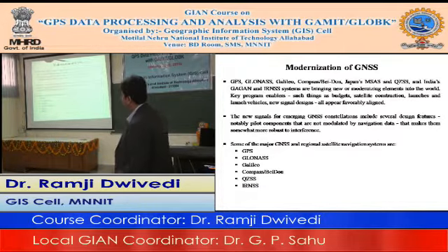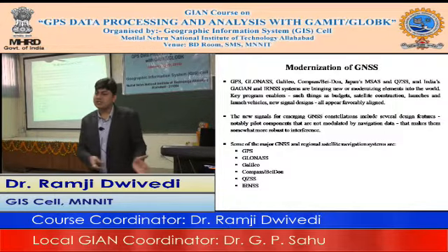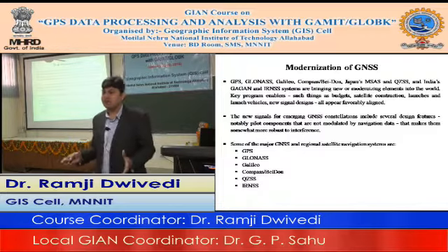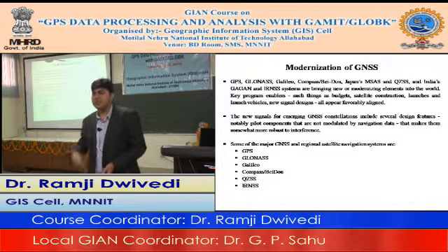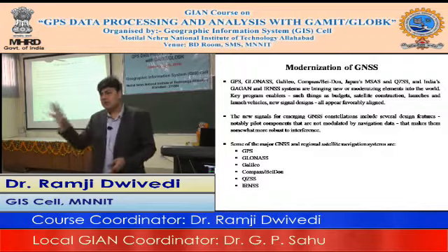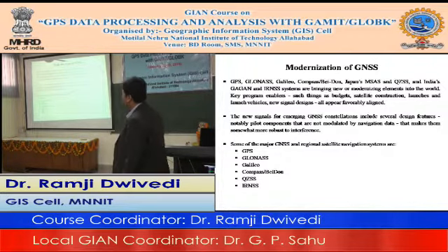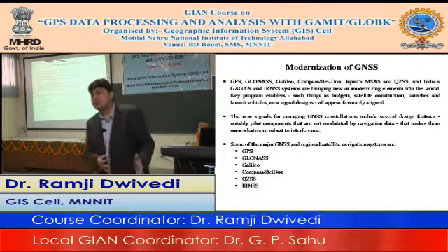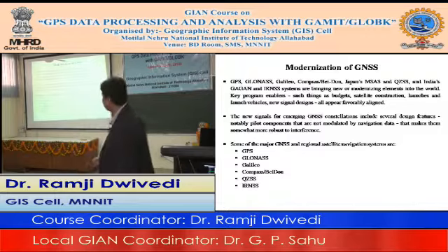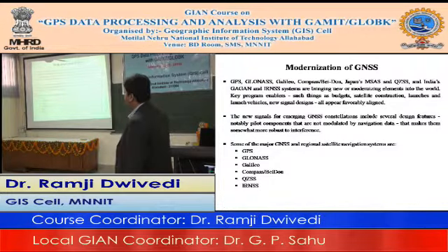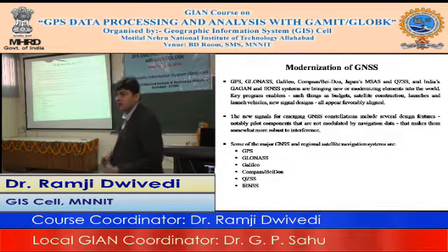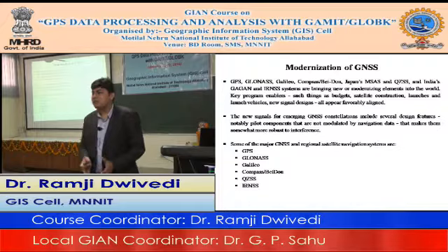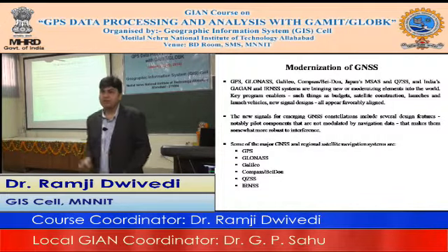Okay, so another section which we are discussing is the modernization of GNSS. Nowadays, if you purchase, let's say we have purchased a base station called NetR9, which has the capability of accessing GPS, GLONASS, Galileo, IRNSS, so many constellations available from different countries. As they are developing, the development from the industry side is also progressing to correlate. Most popularly we always follow GPS, because there is a lot of content available to understand the full functioning based on GPS only.